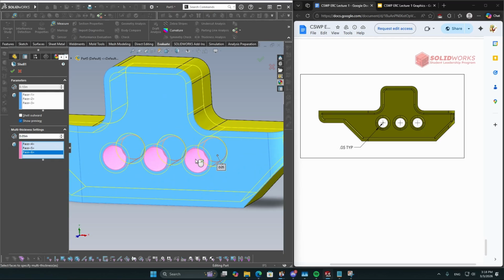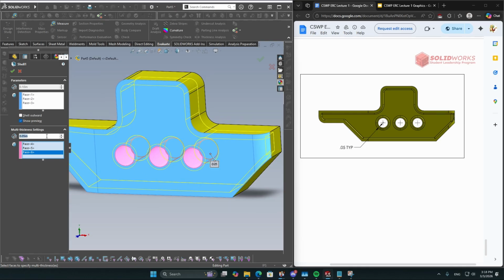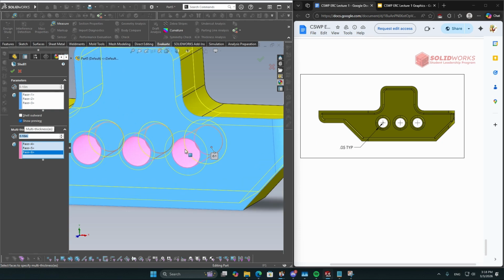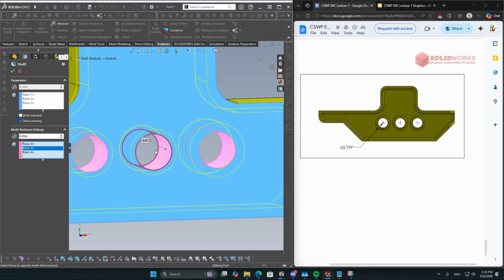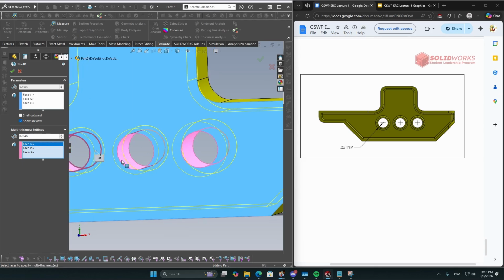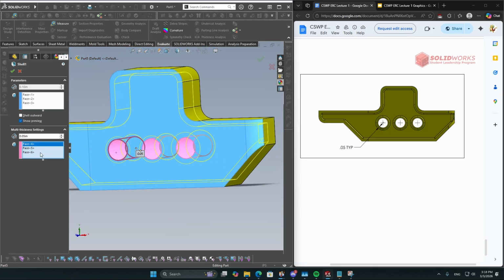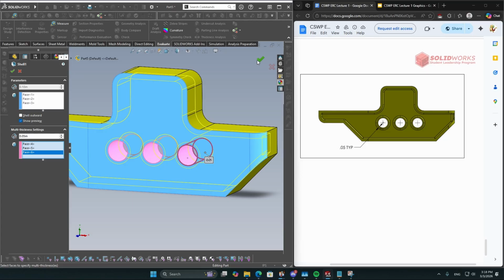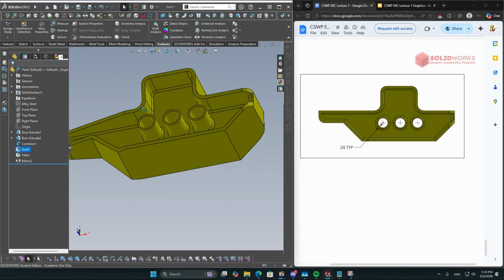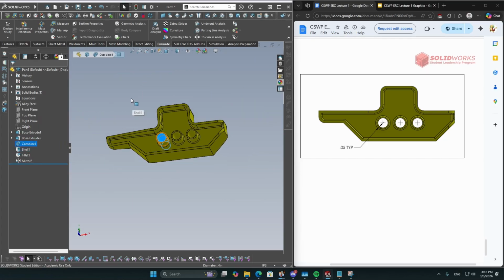And then I'm going to go in and select. The reason I did this first is because if you look, if I change this back to 0.1, it only changes the one that I'm currently selecting. So if I then switch to phase 5, you can see it's individually dimensioning everything. So if I add that dimension first, it avoids this issue of having to individually add the 0.05 inch to everything here. So to now confirm it, and would you look at that, much smaller portholes.